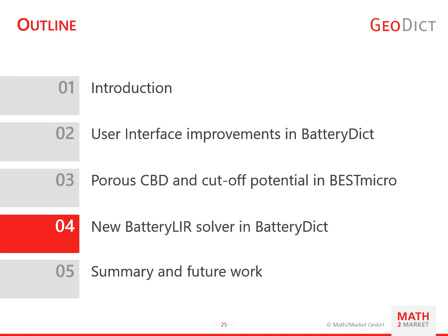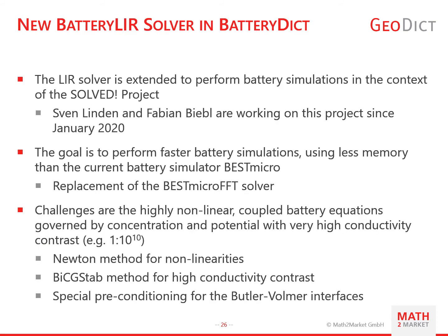In the fourth part of the presentation, I would like to introduce the new battery solver in GeoDict, also called BatteryLeaR. The BatteryLeaR solver was started by Fabian Wiebel and myself at the beginning of this year within the SolveLeaR project. The goal is to replace the BEST micro-FFT solver, which is no longer developed and which is also not part of BatteryDict in GeoDict 21. The solver should have comparable or faster runtimes using less memory than the BEST microsolver.